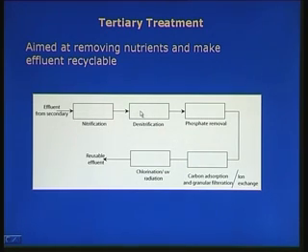After that, the effluent from the secondary treatment is allowed to go to a unit called phosphate removal. The phosphate removal plant could be biological, physical, or chemical in nature. Biological phosphorus removal is normally employed. Phosphorus also causes excess algal growth. So, I am removing the nitrate as nitrogen gas, and phosphate is also removed by the microorganisms.